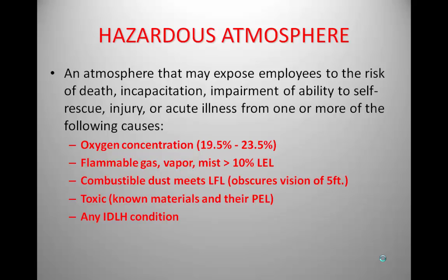The good news about oxygen enriched atmospheres is all of these cases are mechanically induced. Confined spaces don't naturally produce oxygen. So if we have an oxygen enriched atmosphere, we need to find the source, and hopefully we can isolate the source. An example, a person doing a hot work permit in a confined space, so they're using an oxy-acetylene cutting torch.